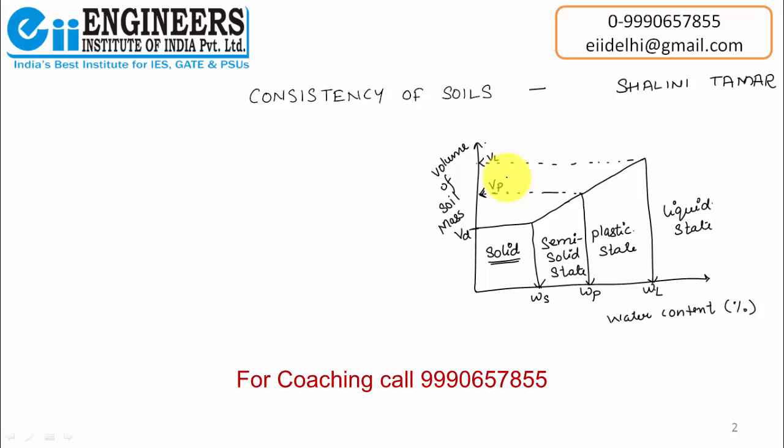The liquid limit WL is defined as the minimum water content at which the soil is still in the liquid state but has a very small shearing strength against flowing. After this WL, if my water content is more than the liquid limit, then my soil will start flowing.